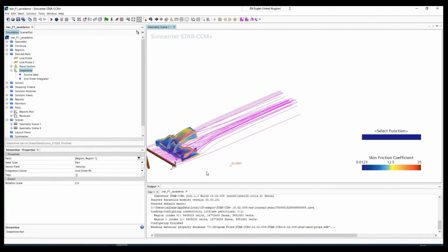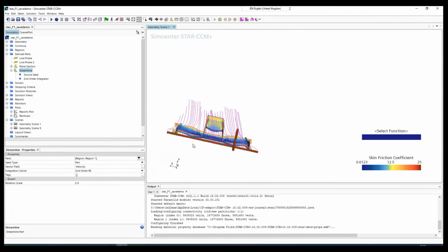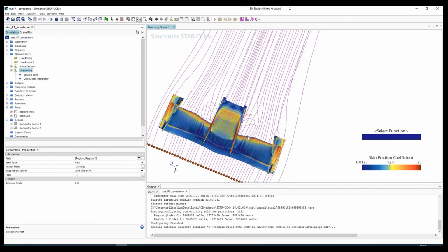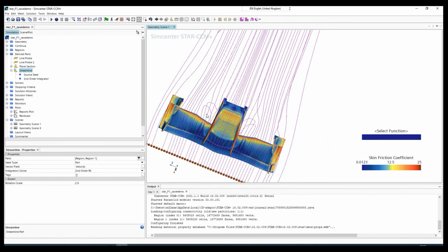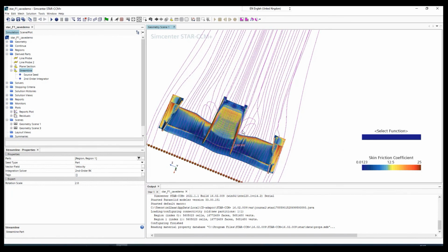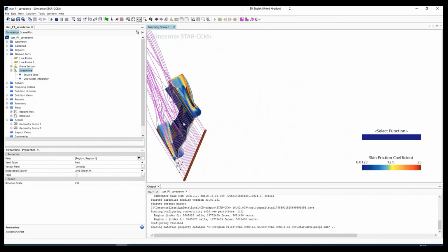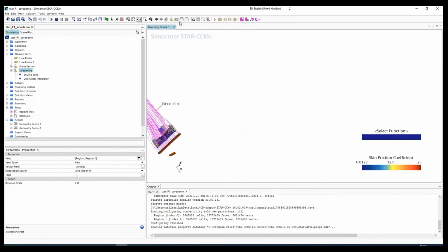And let's see. And you can see the flow separation. Some of the streamlines are going backward and then forward again. So that's the typical flow separation. And if we move towards the downside, let's have a better viewing direction, from negative y and up is negative x.